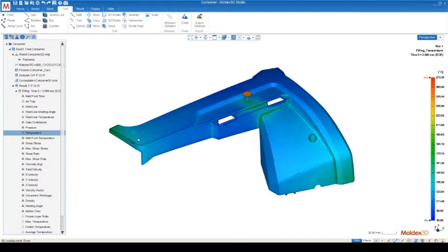There's the cooling effect, where our heating source is at our melt entrance. As we move away from this heating source, we should decrease in temperature. But that's combated by the shear effect, the friction effect that's trying to heat up our melt. So whichever of those effects is more dominant tells us which way we need to slide our filling time.